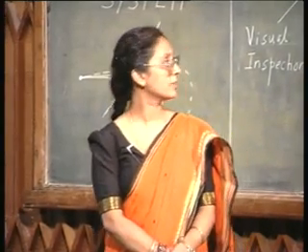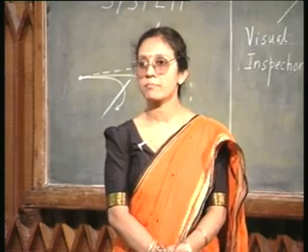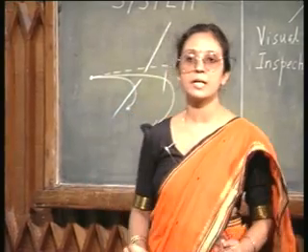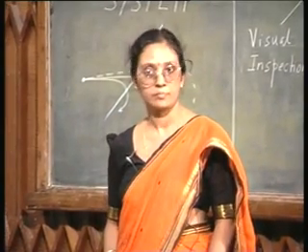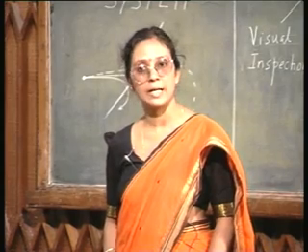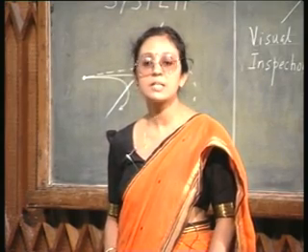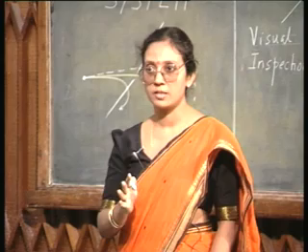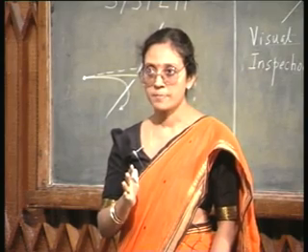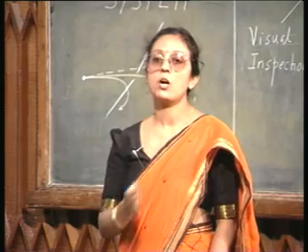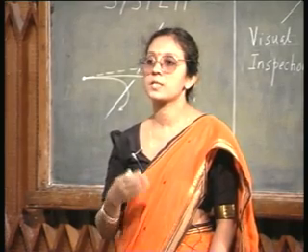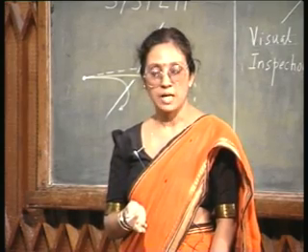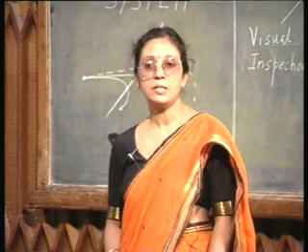I have to get back the electronic activity, that is I have to get the active carrier concentration. You see, I may have put so many dopants inside the semiconductor by ion implantation, but they are not electronically active. That is why the resistivity is very high, rho is very high. I must get the active carrier concentration. Okay. Secondly, the mobility of that damaged region will be extremely low. I must get back the expected high mobility, and then I must get back the expected carrier lifetime.